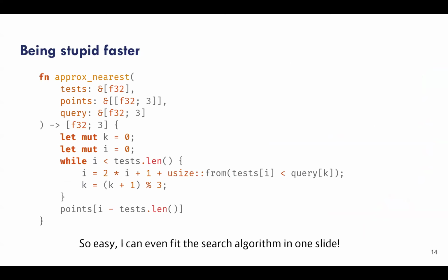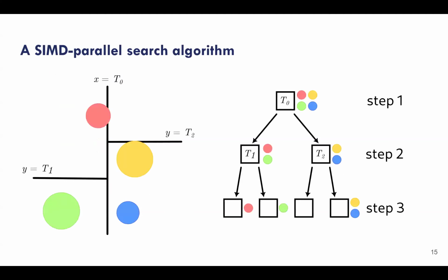But even better, before I get to the problems, is that this search algorithm has an explicit bound on how many times we do that main while loop. So we can actually parallelize the search algorithm. We can search through this tree in parallel across a batch of spheres of our robot, and we can get great speedups.